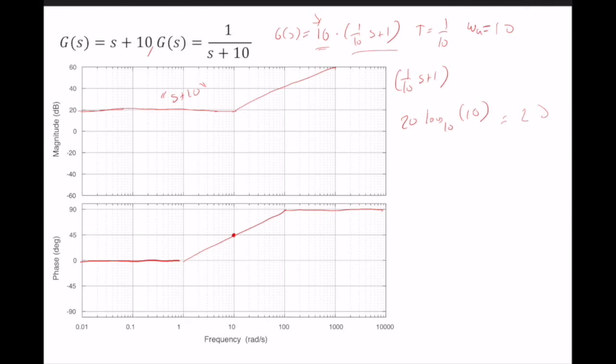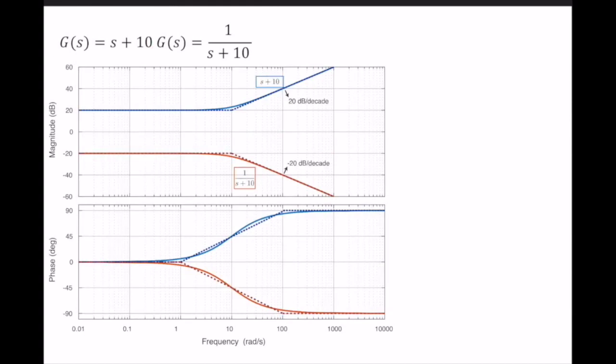So if you remember, if I have g of s and I want 1 over g of s, in both magnitude and phase, I look at the 0 dB line and the 0 degrees line. I take the mirror of g to obtain 1 over g. So if I follow this, I need to have this. I'm just mirroring with respect to that, as you can see. And I need to have something like this for the phase. If everything is correct, let's check. It's correct. Everything is fine.